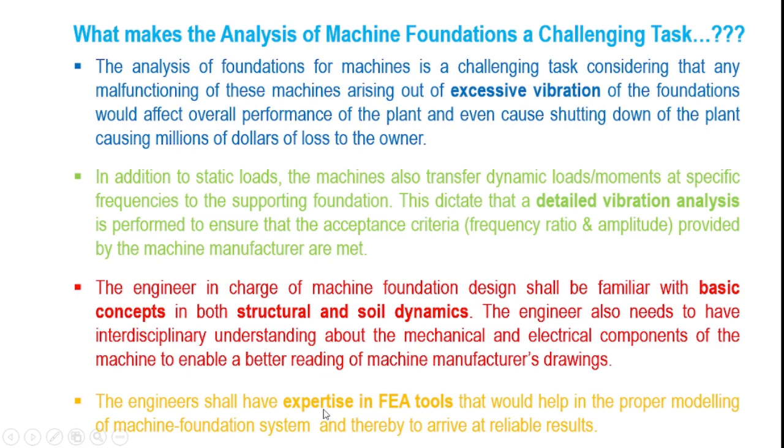And finally, the engineers shall have expertise. I don't say expertise, but even a good understanding of the use of FEA tools is good enough. That would help in the proper modeling of the machine foundation system, and thereby to arrive at reliable results. So here I would like to tell you that maybe for a simple foundation, you can use hand calculations. But from my experience, in almost 90% of cases I've used FEA tools. For example, we have used Abaqus, we have used ANSYS, we have used SAP2000 for the FEA modeling of these machine foundations.